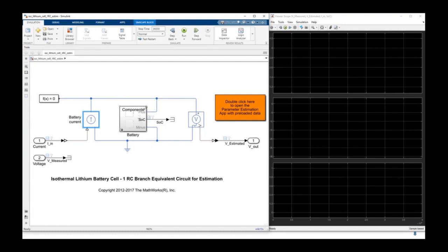After that, when we drain energy out of the battery, the voltage difference that you can see here, measured by this voltage sensor, will be provided as the output estimated voltage. The goal for us is to compare that this estimated voltage is the same as the real voltage we measured on the battery when we did the real measurement. And this is the reference voltage. So we need to compare both of them.